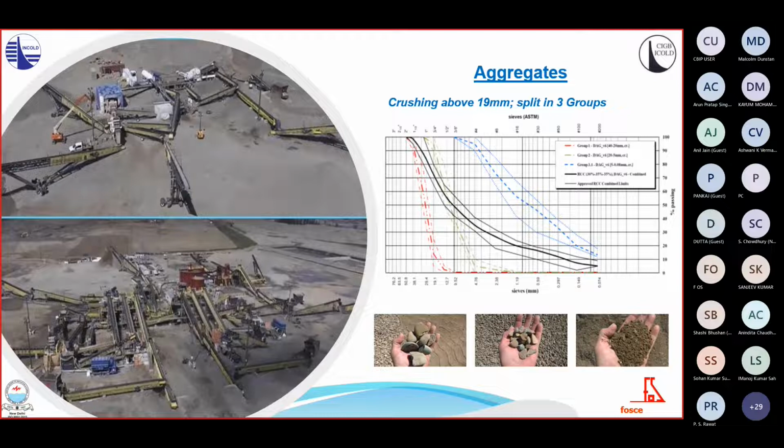A modification was proposed in the specification of the aggregates, aiming specifically to improve these two issues. First, the less rounded coarse aggregate to control segregation, and second, the production of better shaped crushed fines to reduce the amount of natural fines that were demanding a high water content in the mixes.